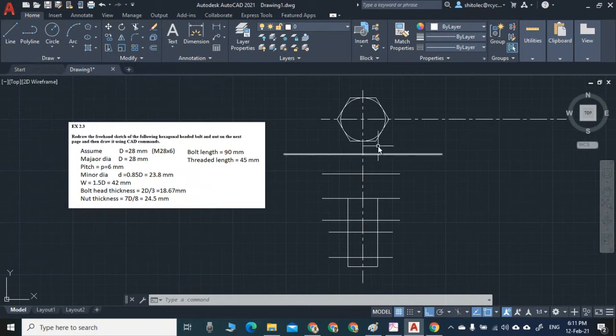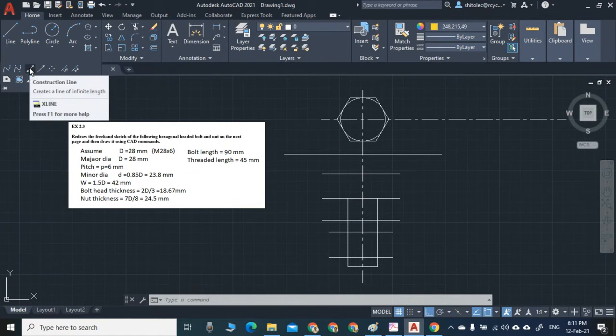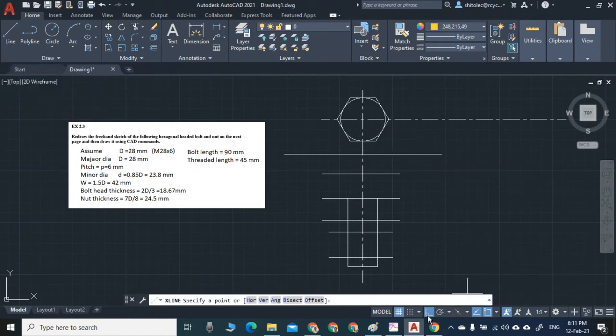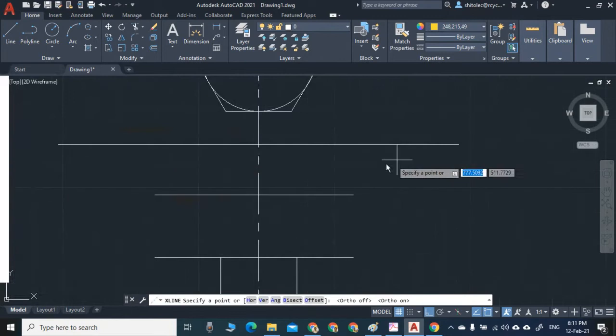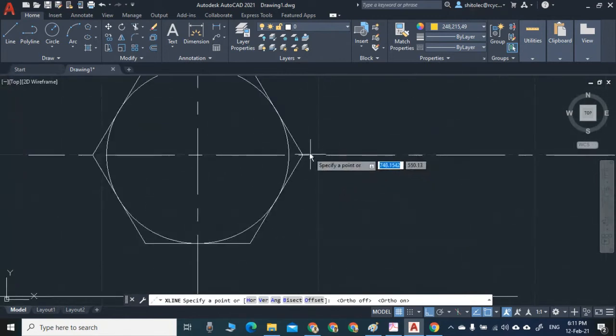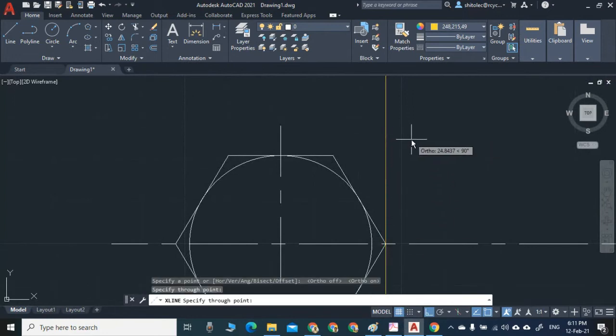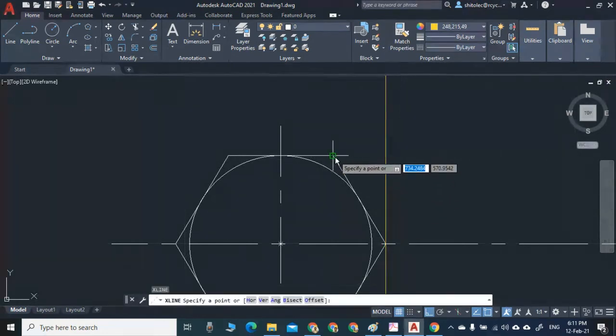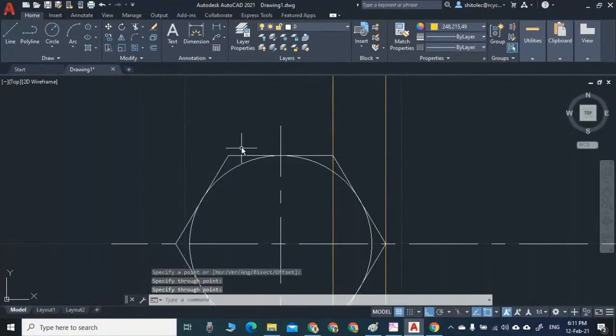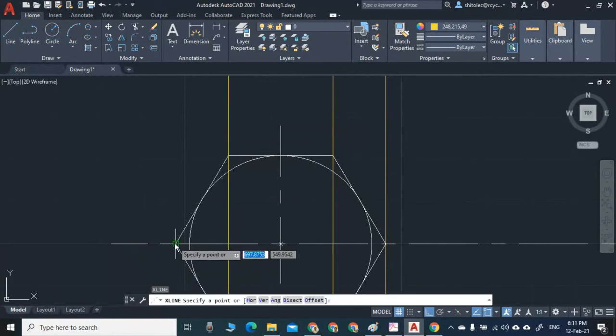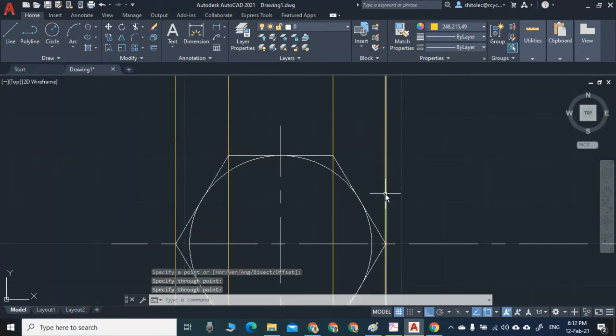Now I will project this line down by using a construction line. So click on yellow, and this is a construction line, use and throw. So click this construction line and make sure the ortho is on, and zoom. So whatever the points I see, 4 points, I need to project it down. So here and this line, enter. To repeat command, enter. This edge corner I can see, enter, enter. This corner I can see from top. This corner I can see from top.